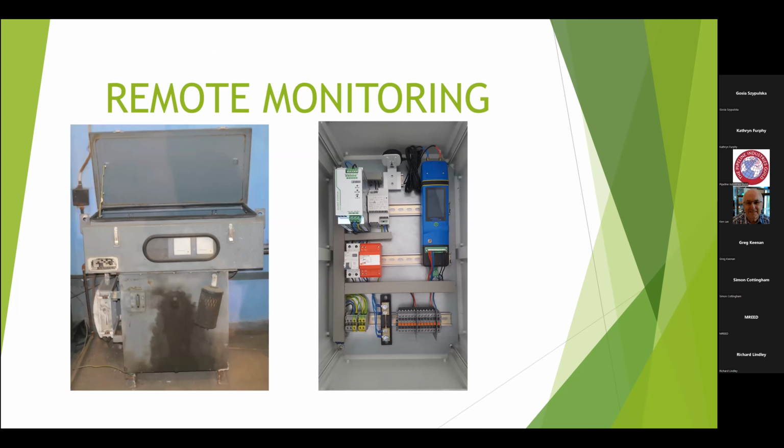They can either be powered by an internal battery, powered from the solar power system, or connected to the mains. Now, the picture on the left shows an old-fashioned transformer rectifier, which is filled with oil to keep the components cool. And you change the output on it by switching it off, unbolting a metal link, a copper link between different terminals, and then connecting them up again and seeing what happened. Very coarse, but they are still in operation. Some of these are 60 years old and still working fine. Sadly, they're hardly ever maintained properly.